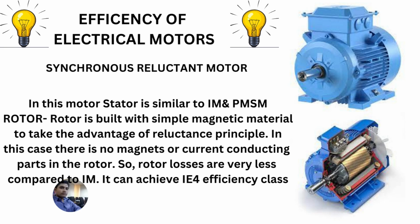Synchronous reluctance motor. In this motor, the stator is similar to the induction motor and permanent magnet synchronous motor. But here the rotor is built with a simple magnetic material to take advantage of the reluctance principle. In this case, there are no magnets or current conducting parts in the rotor, so the rotor losses are very less compared to the induction motor. It can achieve IE4 efficiency class.